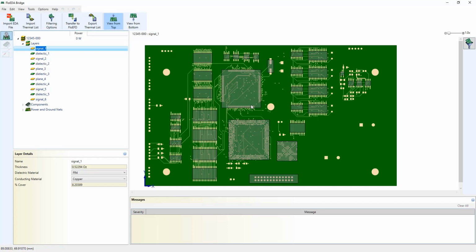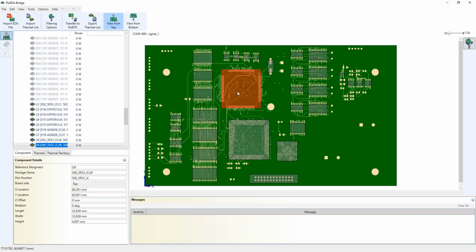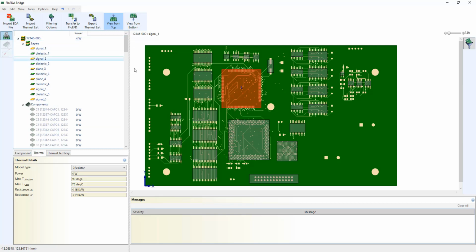The information is imported and used to create a representative thermal model of the electronics subassembly. For example, a component can be picked and a power dissipation defined. If 2-resistor thermal data is present on a datasheet, this can be inputted here for the junction to board and junction to case thermal pathways. A tally of the power is kept and displayed.